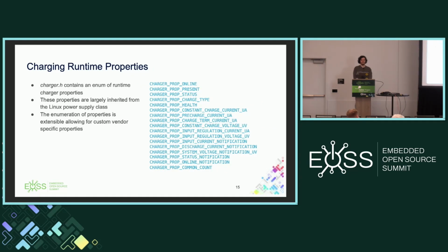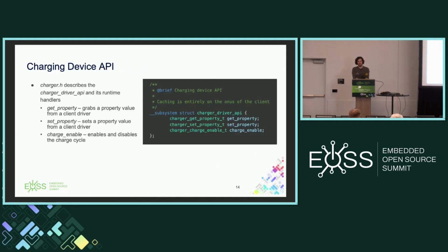Sorry, online property versus online notification. That one was added fairly recently. And it's necessary in Zephyr because of that specific comment right above the charger driver API. There it says caching is entirely on the onus of the client.